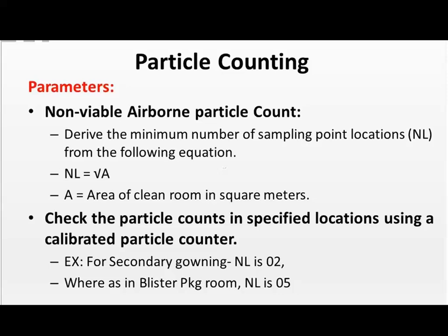And of course, if you have specified locations with particular types of activity going on, you want to sample there. Once you have gathered enough data, then you can back off and only sample these areas. You can then put your clean room on a rotational basis and sample on a rotational basis, but you want to make sure that you are getting these areas weekly.